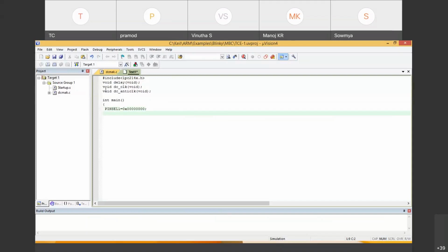So next, once it is done, I need to select IODIR, correct? IODIR 0, it is associated with port 0. Now which value should I feed this? I will use pins P0.30 and P0.31. Last two pins should be high. For that, can I write like this? I'll write 0xC0000000.